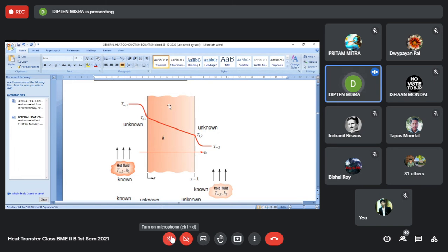We may try to measure the temperature by some device. But if we put a temperature measuring device on this wall, what it will give is an average temperature of the surrounding and the inside of the wall. If you touch a measuring device over here, if you put some thermometer bulb over here, then it will pick up energy from the wall, it will pick up energy from the surrounding air. So the temperature that it will indicate is some kind of an average temperature of the surrounding air versus the wall temperature. So normally what people prefer is not to know the temperature on the wall.